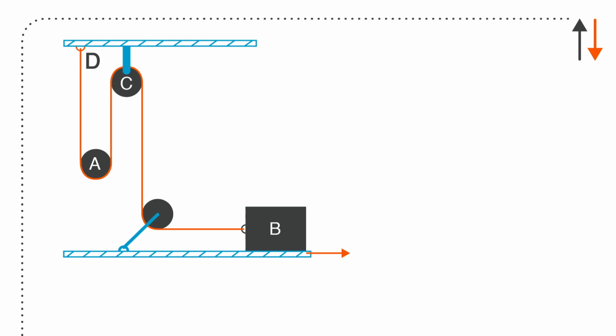The thing that we spent a bit of time on was absolute dependent motion. The orange cord is wrapped around pulley A, pulley C, the corner pulley, and attached to B at one end and D at the ceiling at the other. C is fixed in position. And if I look at that, I can say, well, I have a constant length to this position about the center of C. I'm not including these things here, but they're constant, so I'll probably ignore them later. I have SA, H, and SB.